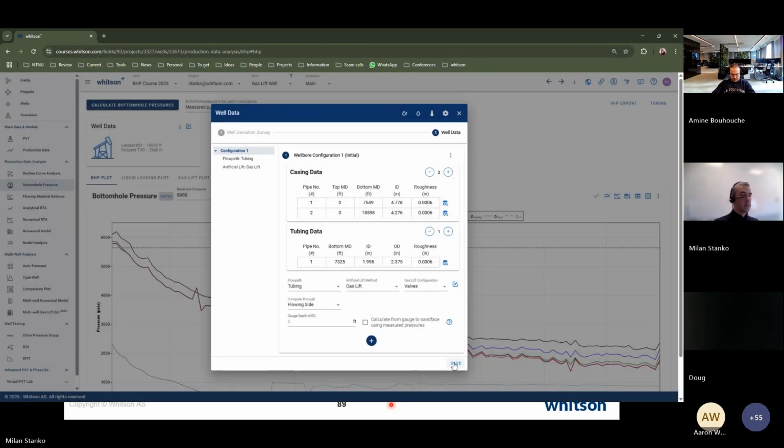And in many cases in your valve tally, like in your Excel sheet where you have the valve details, you'll see that the last valve is an orifice. It's not really a valve, it's just an orifice, so you know that valve is always open. So it's not just an artifact of a calculation; many times it's actually the case that you have it installed as an orifice and not as a valve.